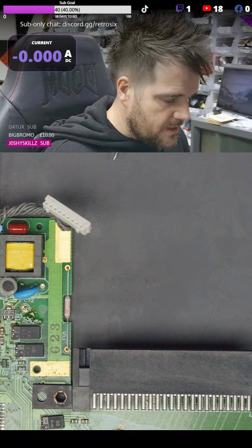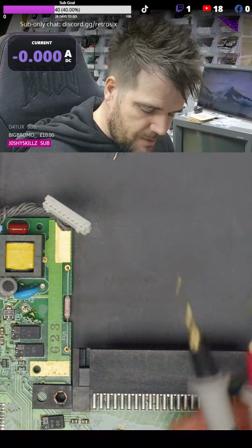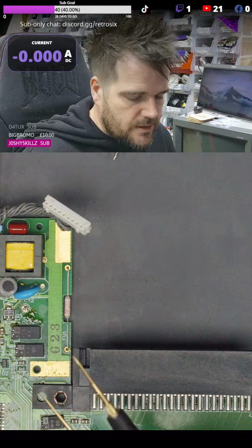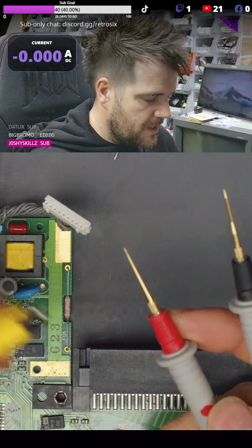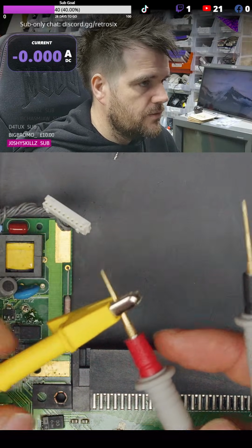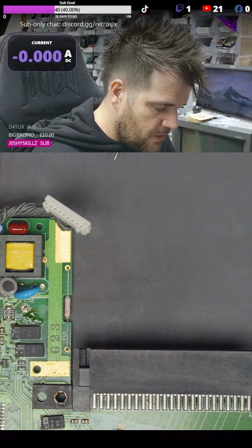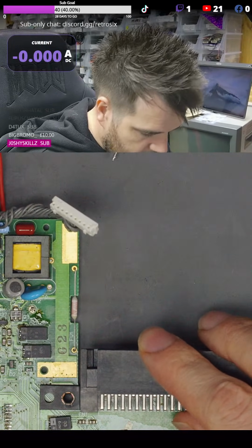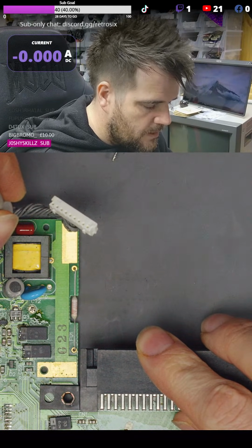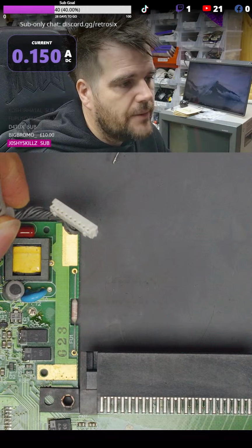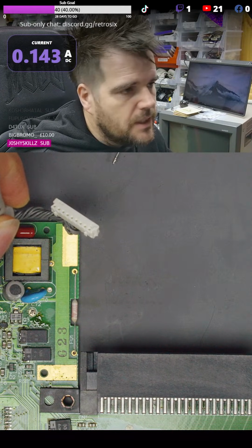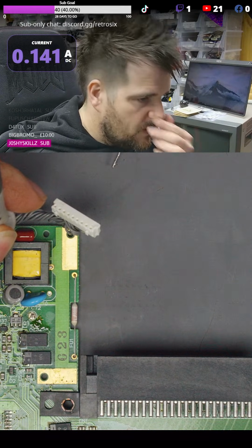Get these leads. I covered this when we went over multimeters, but now instead of injecting 5 volts straight to the board, I'm going to pass 5 volts through the red, so this is going through the meter. And now when I touch on the 5 volts on the board, say here, you can see there we get 150 milliamps. That would be fairly normal.